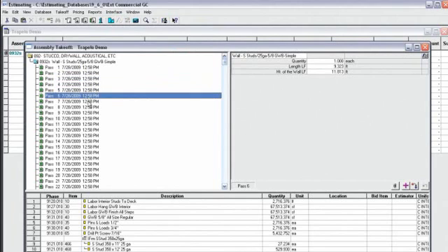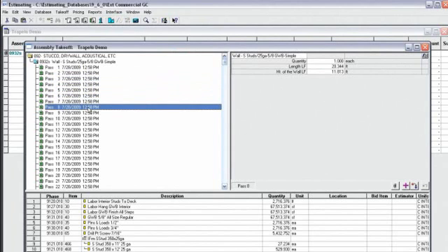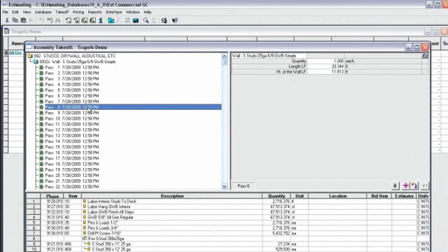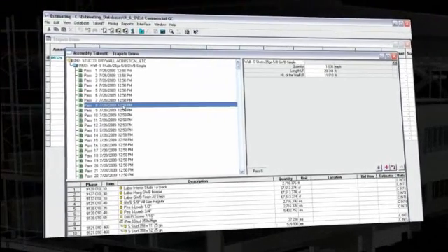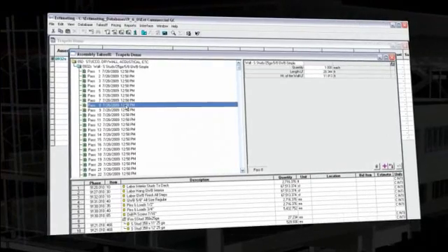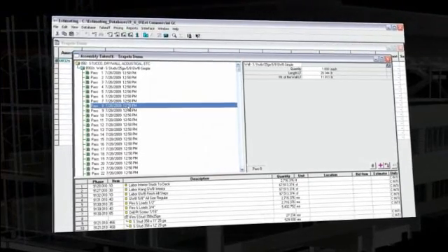Therefore, by using Autodesk's Revit platform for BIM, object quantities, doors, windows, walls, etc., and dimensions are stored within the model, which can be extracted using Autodesk QTO for use within Sage Timberline Office Estimating. Simply drag and drop the model elements to the estimating database for a simple one-time integration setup. Once this mapping is completed, it's stored within Autodesk QTO for use on subsequent projects. Exporting this data to estimating provides a fast, accurate, and automated process for creating cost estimates.